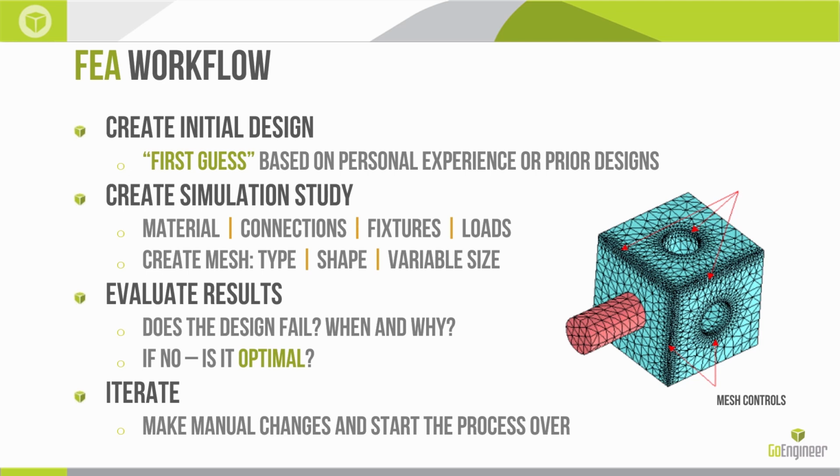So it's not uncommon to incorporate variable mesh sizes, or something in SOLIDWORKS we call mesh controls. And mesh controls allow us to spend more time calculating results where we need them and less time where we don't. So in the cube here, we have a finer mesh control applied to the edges of the model, and then the faces around, and the open cylinders.